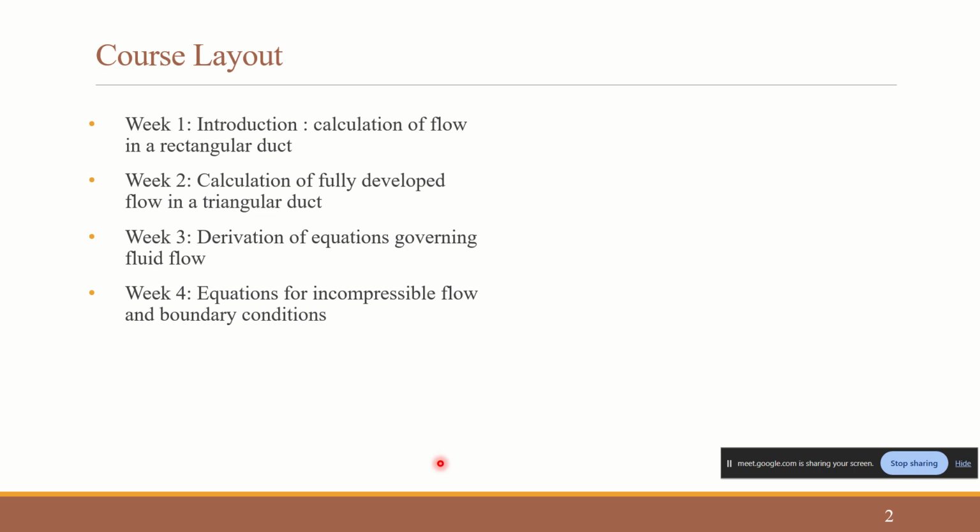So whatever information we know at hand, we give in the form of boundary conditions, that is, we give the values at the boundaries. And for incompressible flow, as we all know, there is no density variation, so it becomes constant. So in the continuity equation, it becomes common, we take it out and the term becomes 0.